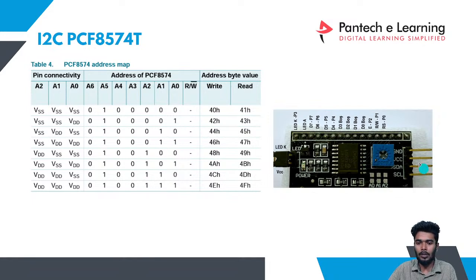Okay, guys, these are the addresses. As I explained in the previous session, with I2C we can connect multiple slaves and multiple masters, right? So consider we connect one master and three I2C modules, the same module, three of them. You can see we have addresses for this module. As I taught in the previous class, the I2C master does not select the slave with a select pin.